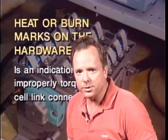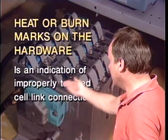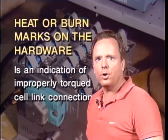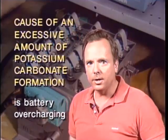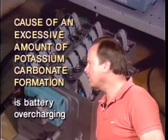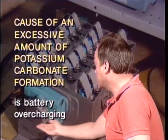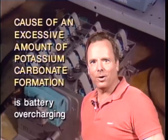Let's assume that you find heat or burn marks on the hardware of a battery. What's that an indication of? Well, it's an indication of improperly torqued cell link connections, and it means you have had some arcing there. What is the most probable cause of an excessive amount of potassium carbonate formation on a battery? And the answer is battery overcharging will cause an excessive amount of potassium carbonate formation.